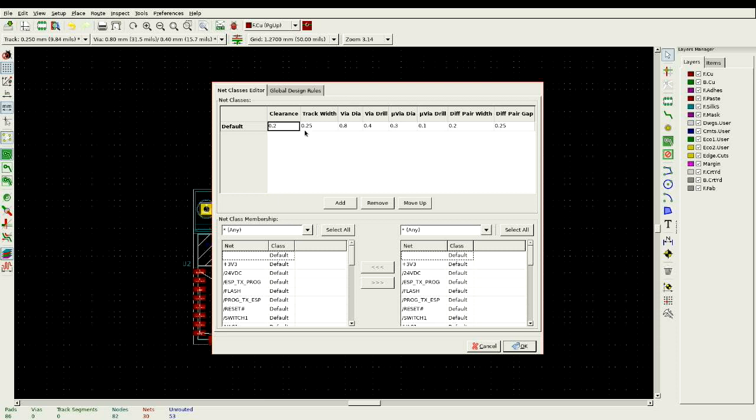If you just enter the design rules as on the diagram, we have 0.15, 0.15, and the via diameter is 0.6, 0.3. So these settings that I'm providing are supported by all of the major prototype houses at their cheapest level. If you need finer pitch, you pay more.